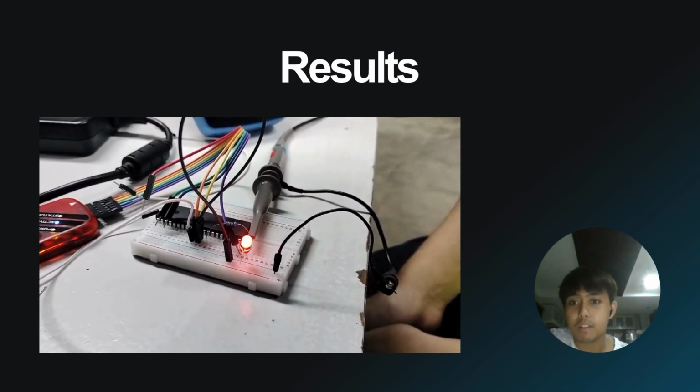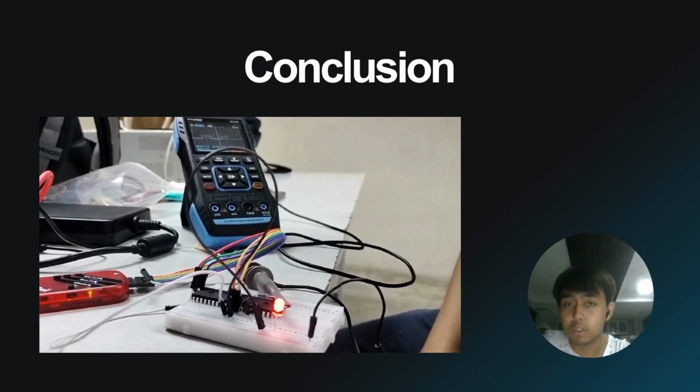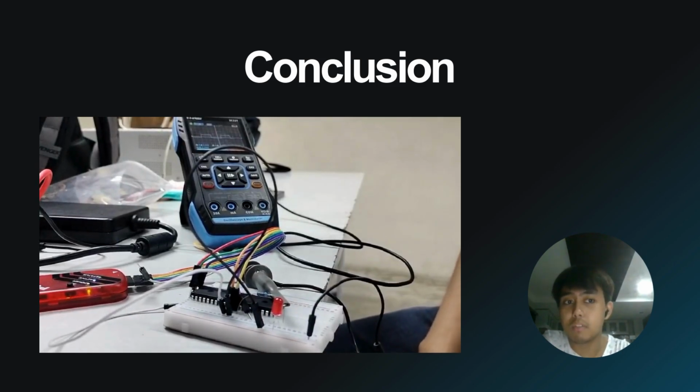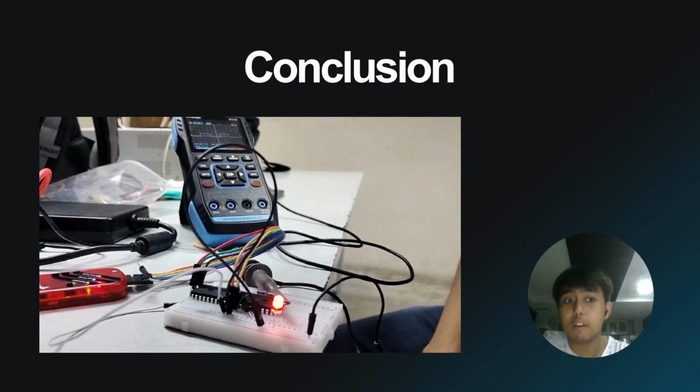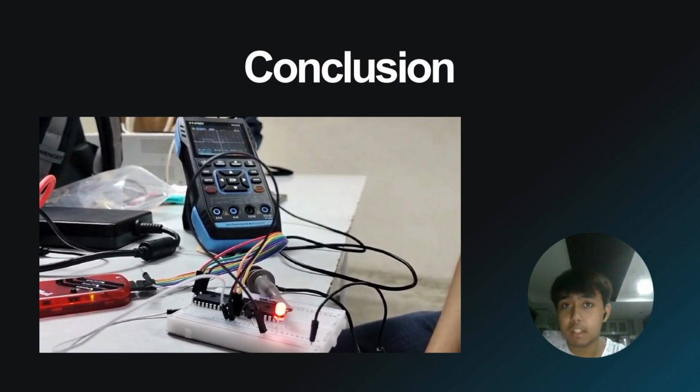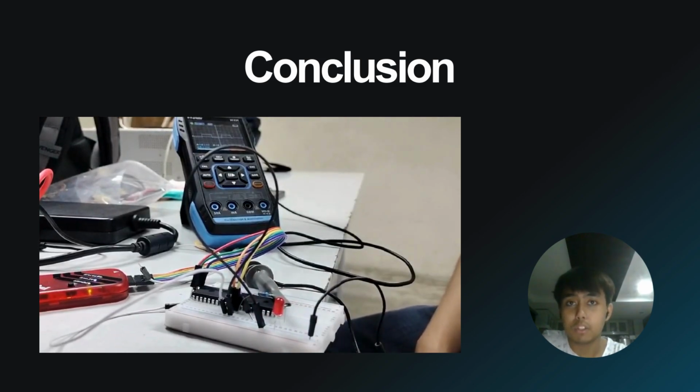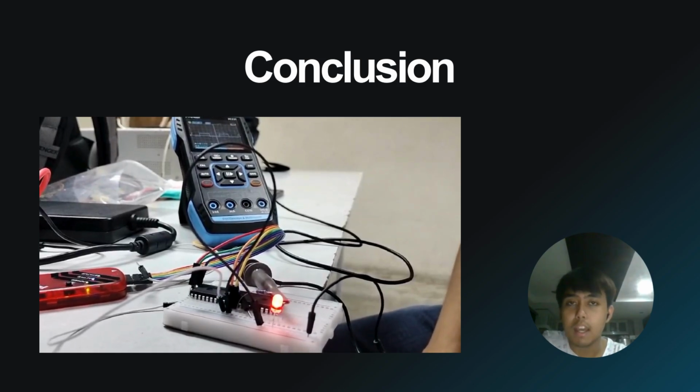In this experimental setup to investigate LED control utilizing delay polling and timer zero interrupts, we constructed this microcontroller circuit. The LED blinked at intervals of 250, 2000, and this time 5000 milliseconds due to delay polling. We suggest using different pins for different code versions, double checking the PIC kit connections, and using templates to uncover issues, and choosing the right version of the MPLAB IPE and IDE to ensure smooth running and compiling of the codes. Thank you very much for listening.